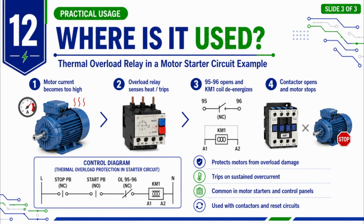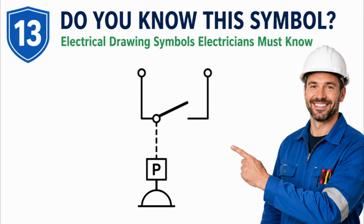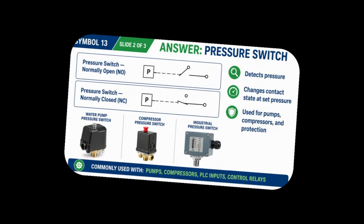Remember, overload relay trips. 95 to 96 opens, motor stops. 97 to 98 closes, trip indication. Now let's look at symbol number 13. You will often see this symbol in pump, compressor, and industrial control circuits. Do you know what it represents? This is a pressure switch.